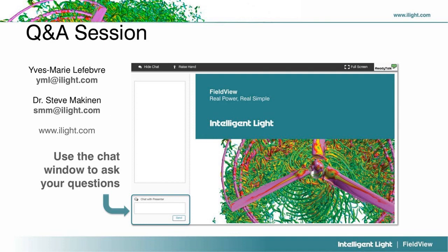data analysis. And also it's possible to use FieldView, for example, as a pre-processing step, and then you can create XDBs. And then from the XDBs, you could even take a subset of information from the XDBs for the data analysis. And if you're not familiar with XDBs, those are just extracts from the entire flow solution at whatever regions you're interested in. Hopefully that answers the question.